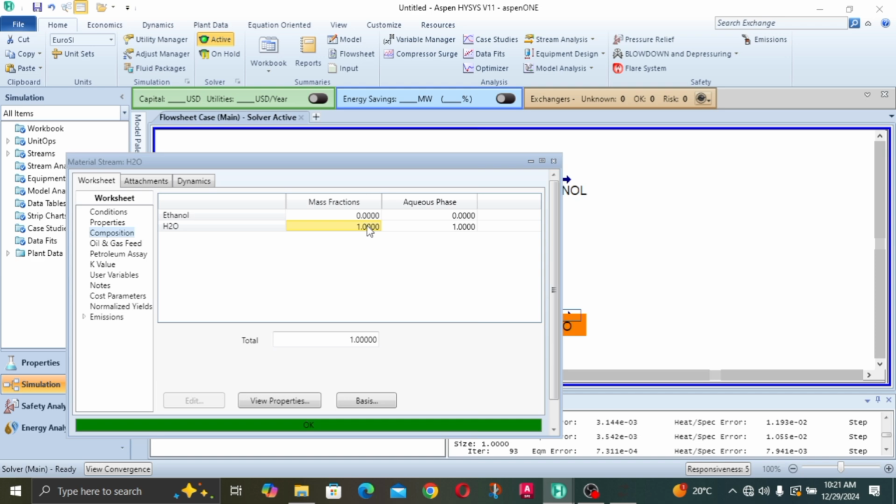Wow. So we have a purity of 100%, but that does not mean we have completely separated them. To know whether we have completely separated them, we will have to check the recovery rate, to know how much out of the total volume of the two components we have in a particular outlet.